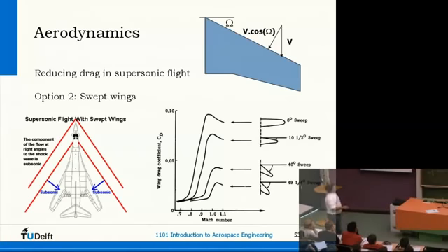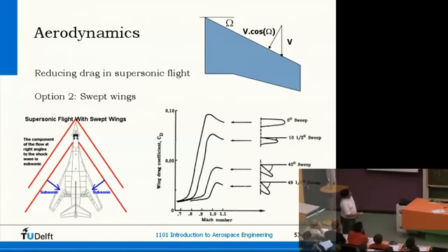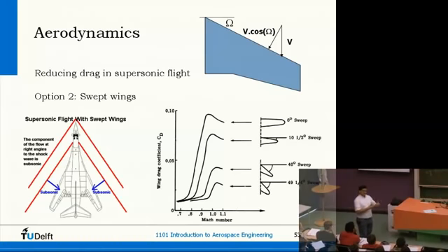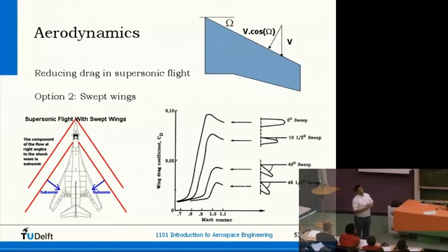Here you see, for instance, the same effect again, where you have drag coefficients which are low at subsonic speeds, but increase significantly when you come close to the speed of sound. And that's why people always experienced some kind of sound barrier. It is very difficult, problematic, to surpass the speed of sound. You also get a lot of buffeting, trembling of the wings. So in the early ages after the Second World War, they were very anxious to go beyond the speed of sound. That's why the Bell X-1 was launched.